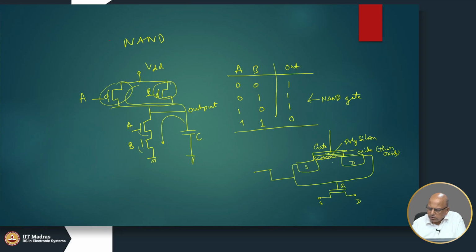It is called metal oxide semiconductor because a long time ago I think this was made of metal, then there was oxide and there was semiconductor. So, this is an NMOS transistor. When you apply a high voltage here, a channel gets formed and conduction will occur. Whereas, when the input is 0, there is not much conduction, there are only minority carriers which are responsible for the current. A small current will flow if you apply a drain to source voltage,